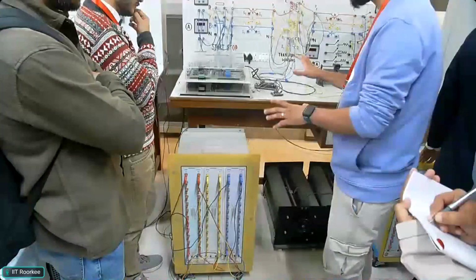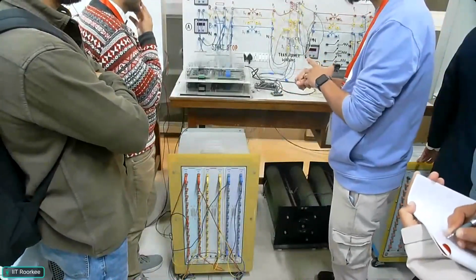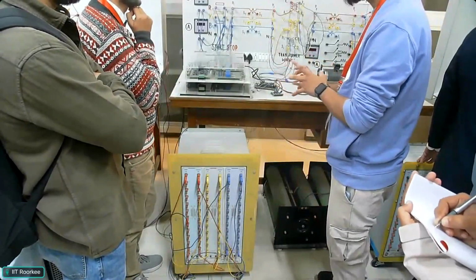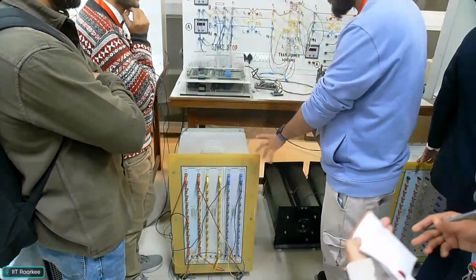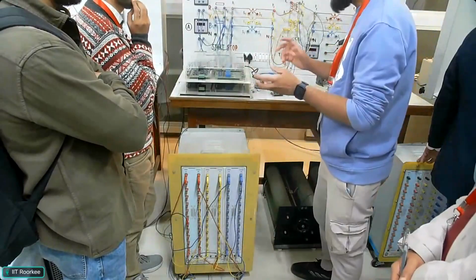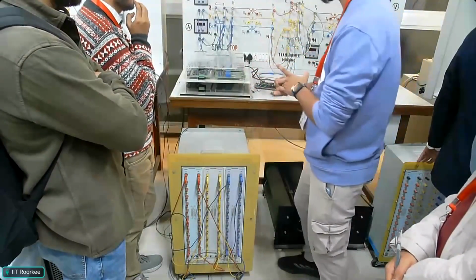So in this transformer setup, we have recorded an inrush peak of 75 amperes and a fault current of around 20 amps. For this transformer rating of 5 kVA, the current rating is 7 amperes, and almost 3 times that, we have created a fault for this setup, and we checked our algorithms.